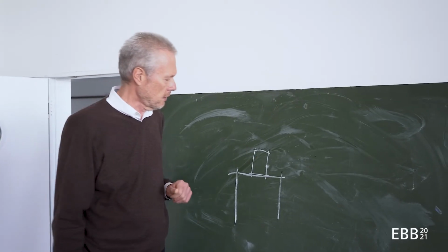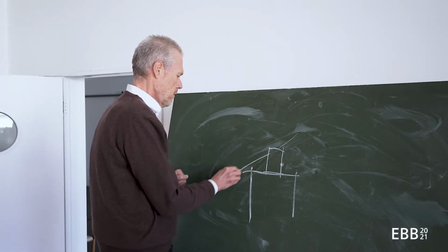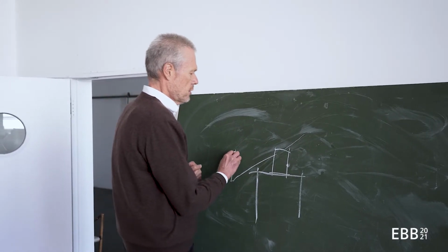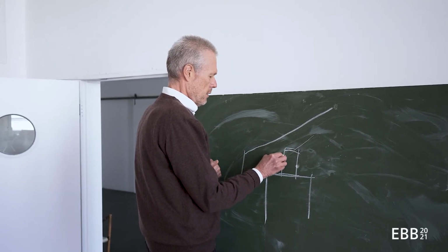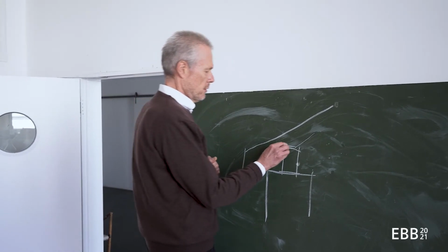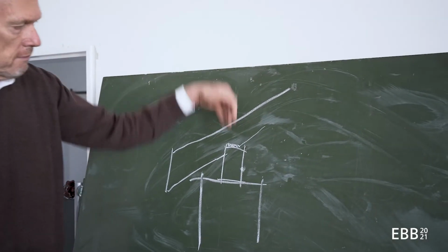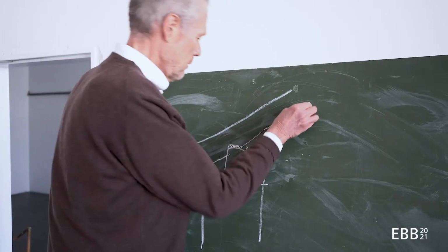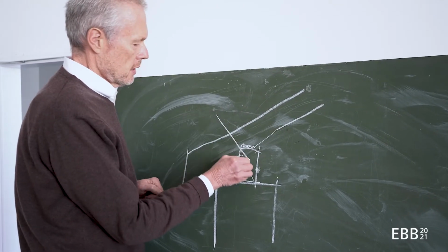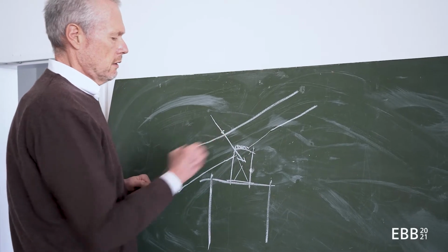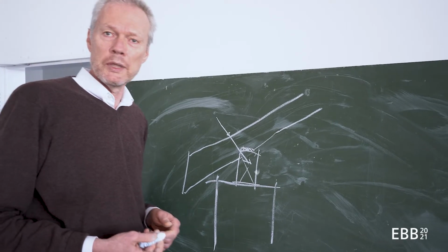I have the lower purlin, and then I have the rafters on top of that. And here once again I'm creating a step joint to assure that by gravity the rafter can rest on the purlin, and then I might secure it with a nail diagonally so it is not lifted up by the wind.